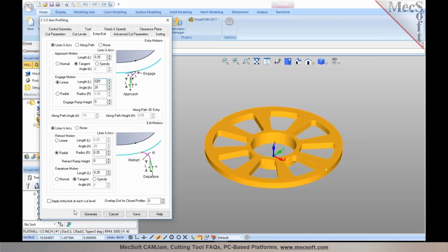Uday, I just wanted to mention that the first motion always has to be a linear motion for the cutter compensation to be turned on. That's why we have the approach motion there that's got a length, a tangent approach motion, which will always be a linear motion. So yeah, controllers cannot apply cutter compensation on an arc, so we have to have a linear motion.